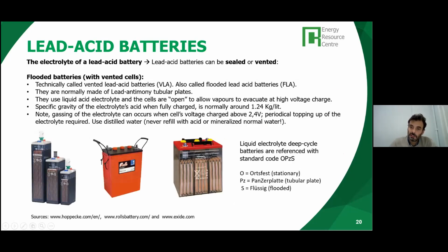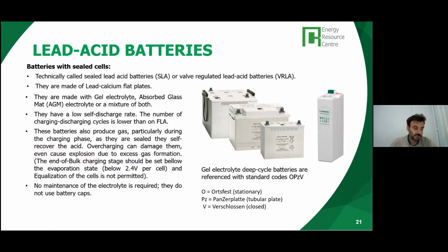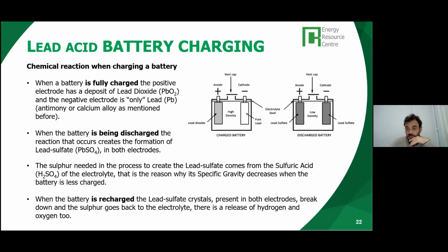Again, as opposed to the OPZS, we have the OPZV. And in this case, the V stands for verschlossen, which means closed in German. So these are closed batteries. We cannot access the battery cell, the electrolyte. This makes these batteries safer, easier to handle, but they have a little bit less performance, less efficiency than the OPZS. So this is again the pros and cons of choosing equipment. In this case, performance versus safety, or ease of maintenance.